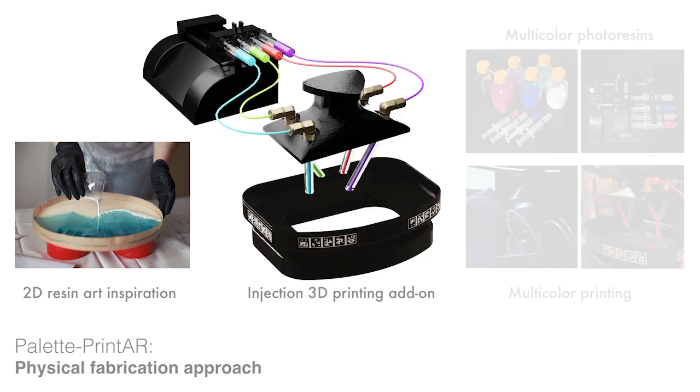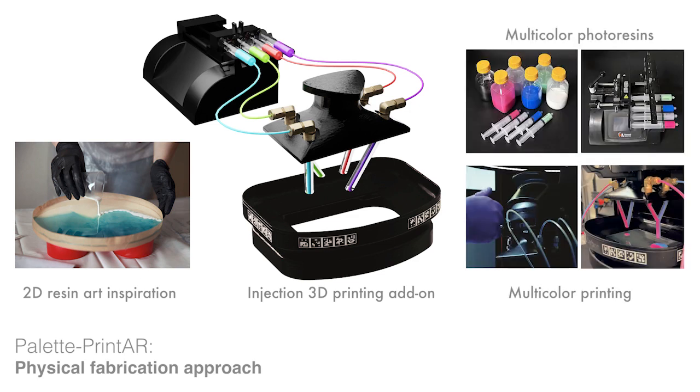Our 3D fabrication approach is an add-on extension to existing stereolithography-based printers, which we equip with syringes for multicolor injection during printing. In our approach, the build platform connected to the syringe pump constitutes the paintbrush, and the resin vat the palette.